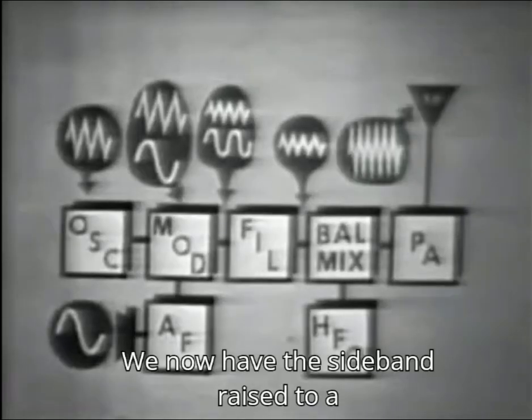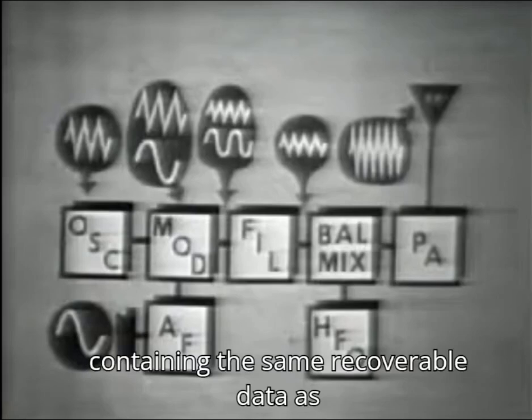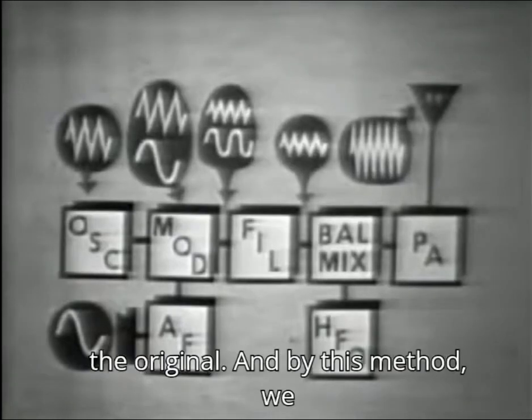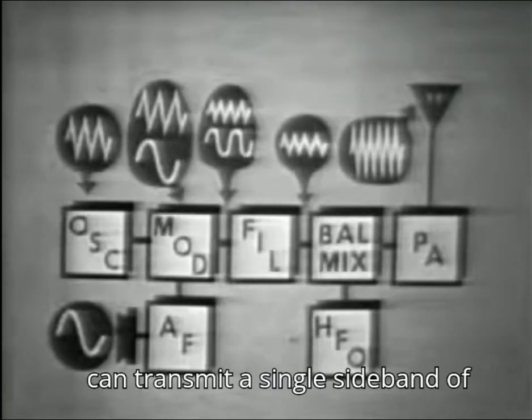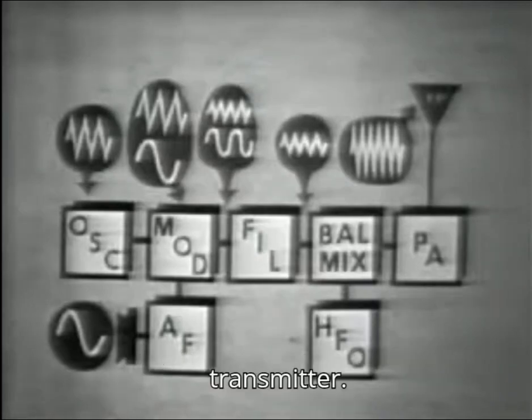We now have the sideband raised to a predetermined higher frequency containing the same recoverable data as the original. And by this method we can transmit a single sideband of any frequency with the full power of the transmitter.